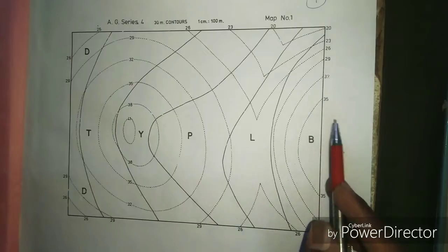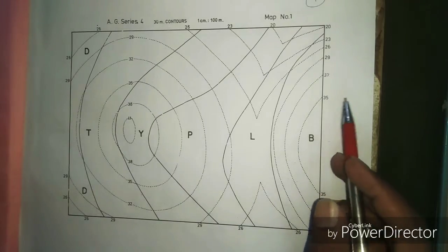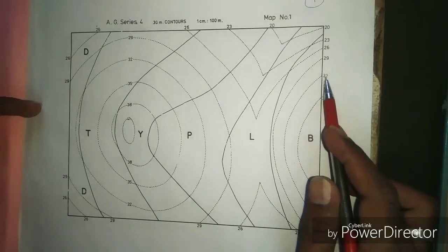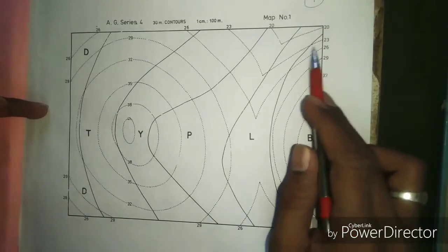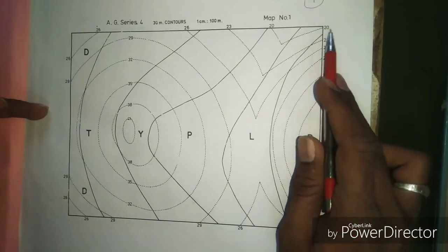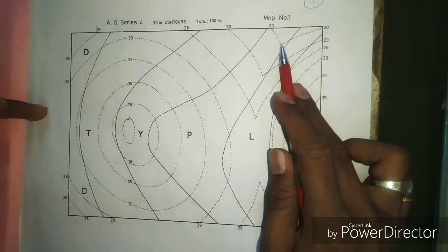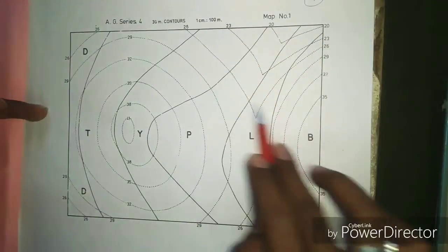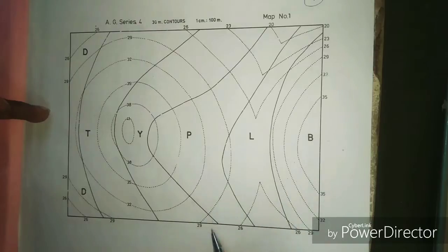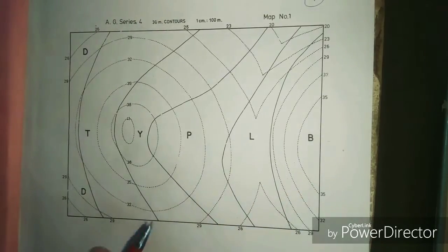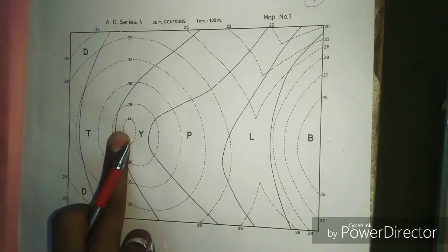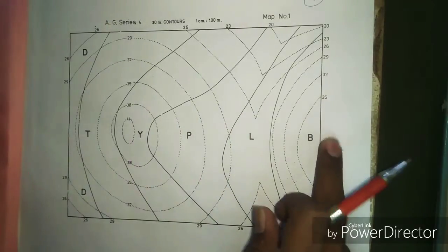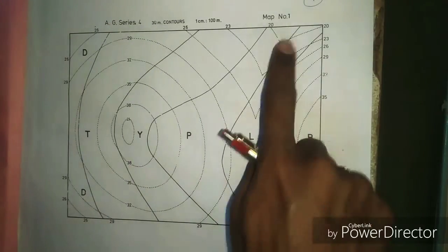These contour lines are in semicircular form here because they show contours of 350 meter, 320 meter, 290 meter, as well as 260, 230 and 200 meters. These contour lines make a V shape because there is a valley on this side of the map and a second valley on this side, because geographically this map contains one isolated hill and a portion of another isolated hill, and these isolated hills give rise to valley number 1 and valley number 2.